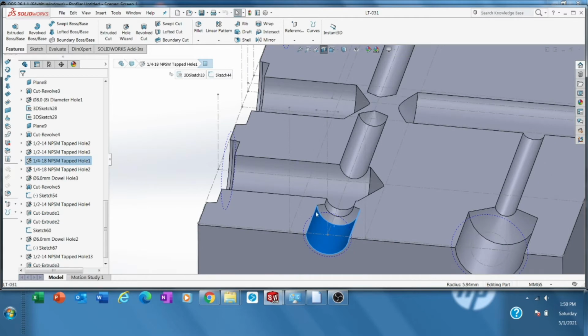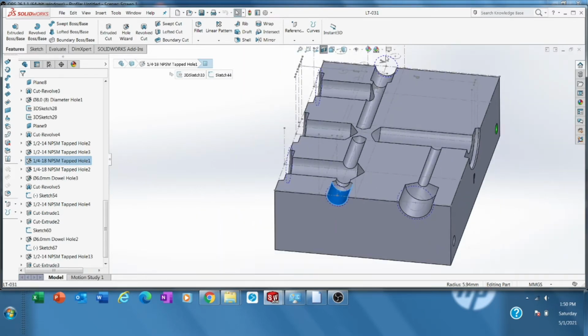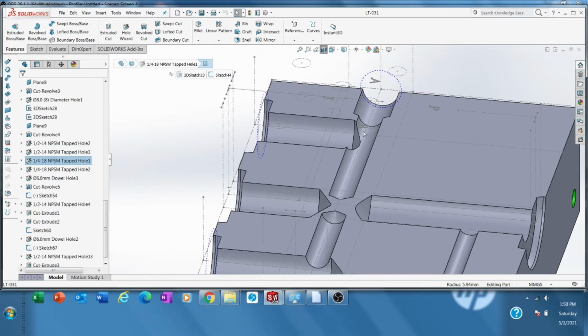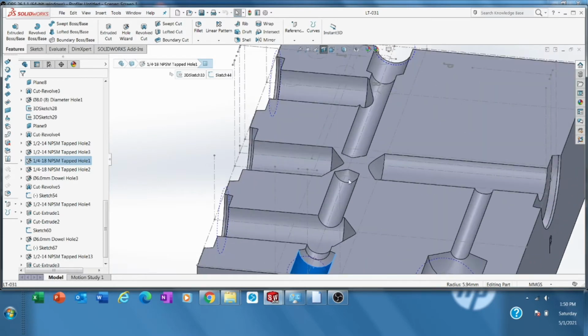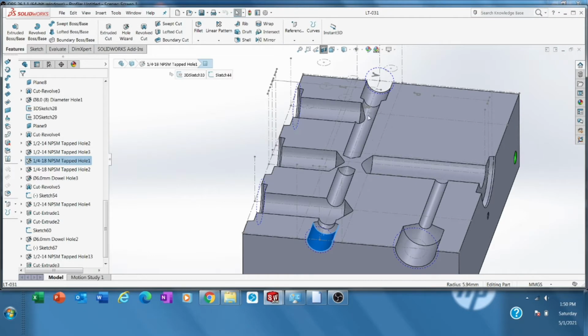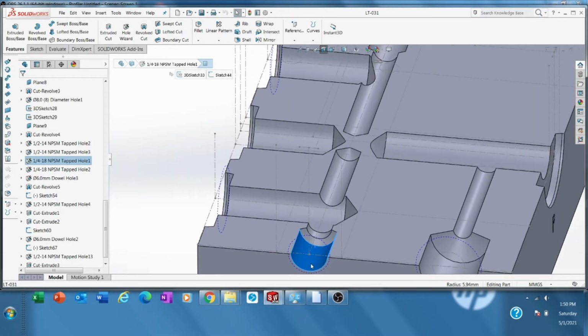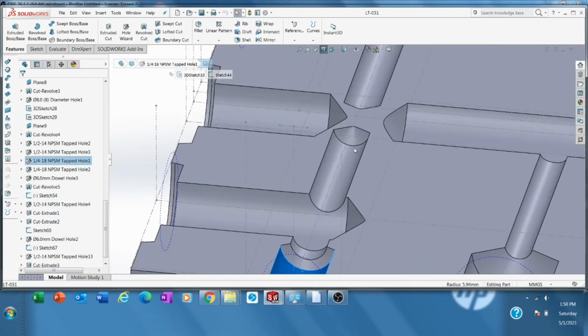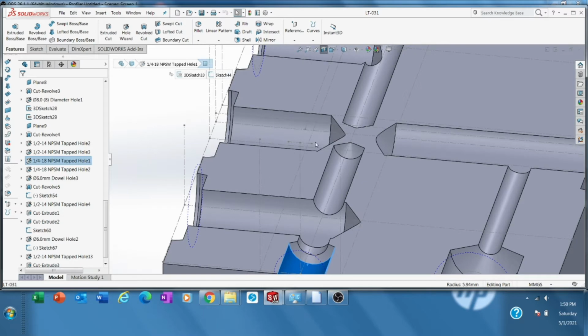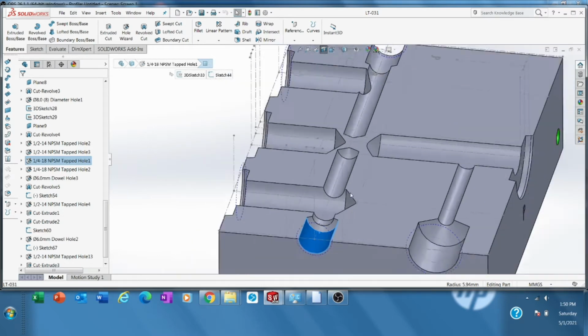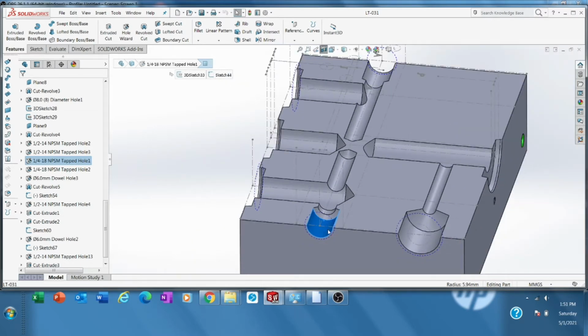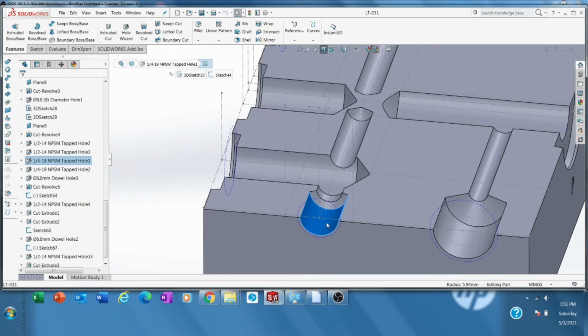Of course, when it is blocked, it will go to another place from here. I will explain later on, because at the top there is also a hole connected to the directional valves. So why did they put it here? Of course, to ensure that there is a connection to the 4 holes here. So they drill it, and then later on they blind it.